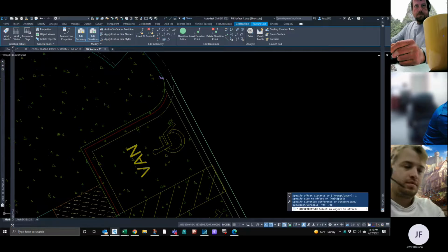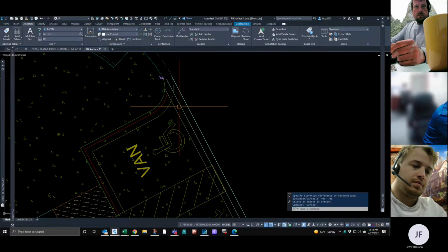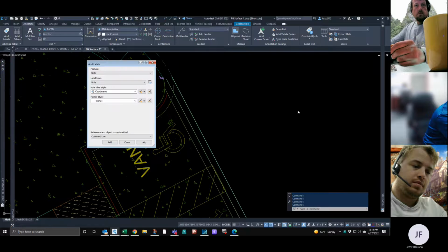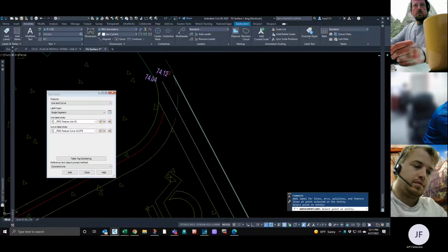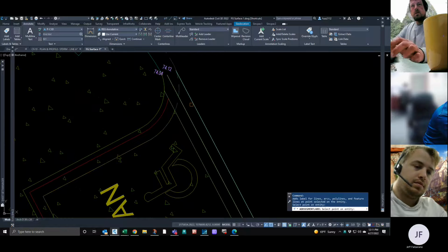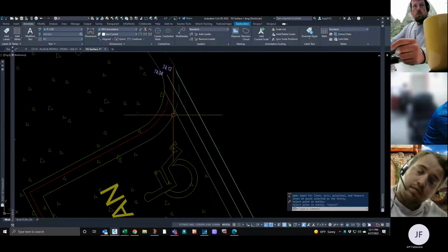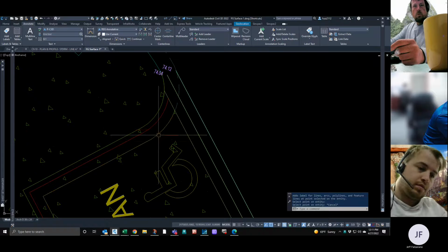And then it drops in your feature line on the other side, so that now you have the outside of your pan in that direction. Let's just label this thing, make sure it did it right. So it's up your 1 inch on that side. We want to do the same thing for the other side, and then we're just going to trim it off on the side where this pan meets the lip of this gutter over here.